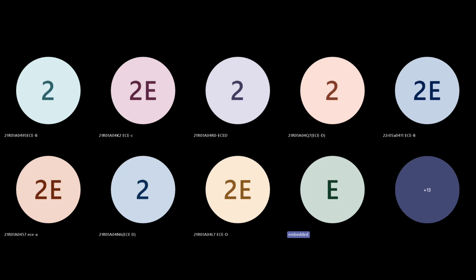through the system bus. In this diagram, you can see the timers, serial ports, and the address and data lines, RAM, on-chip ROM for program code, bus control, oscillator, CPU, and interrupt controls. The external interrupts are here, and T0 and T1. The other pins here are TXD and RxD, and counter inputs are present here at the timers T1 and T0.